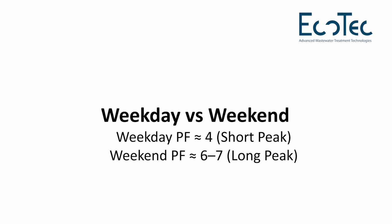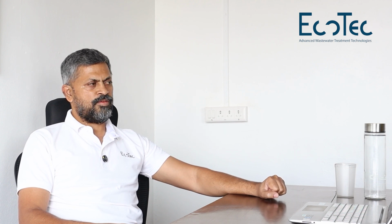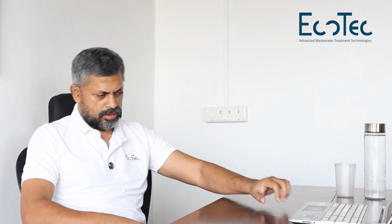These are the reasons why sewage treatment plants fail. They're not failing because of hydraulic reasons alone. They are failing due to peak factor misunderstanding. First, peak factor influences the hydraulic flow, which again influences the biological parameters of the water in the treatment plant. Now let's see what happens to the biological fraction of the treatment plant.